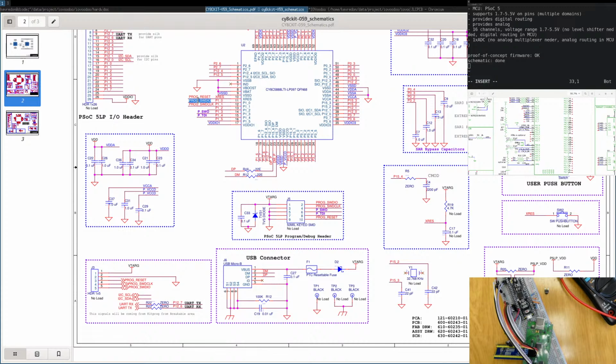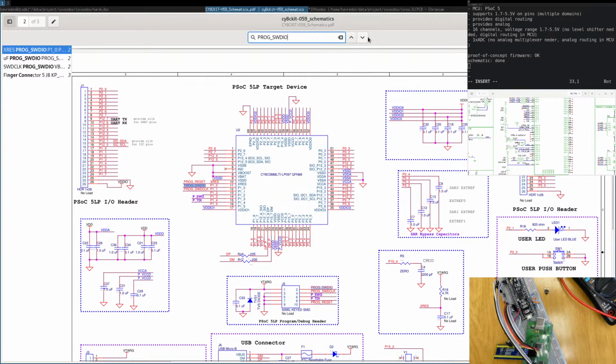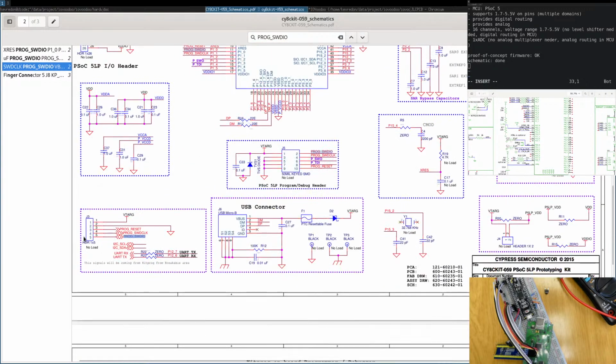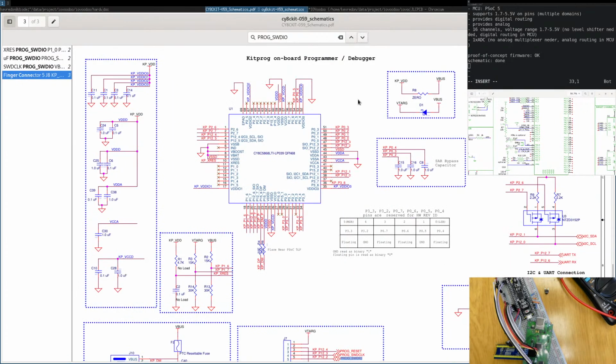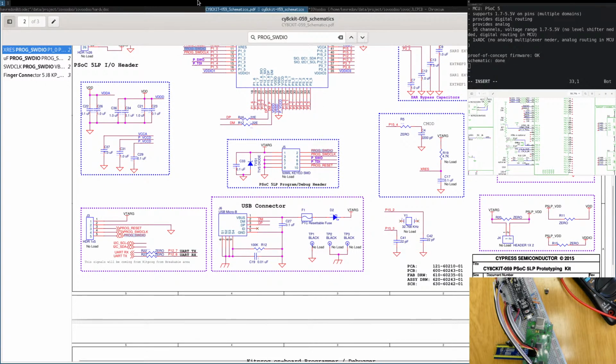You don't have to. I don't know if it's a recommended design from JTAG that the lines are pulled high. So here it's not pulled high. On its own, it is not pulled high.